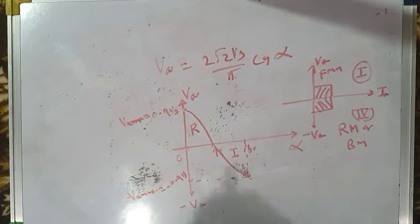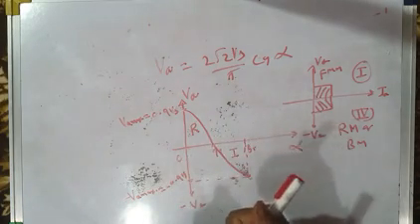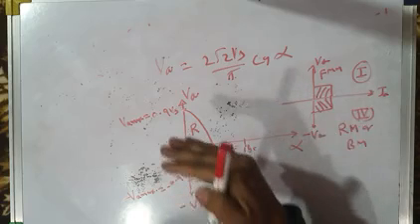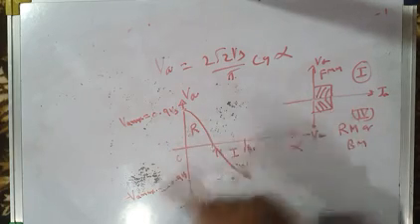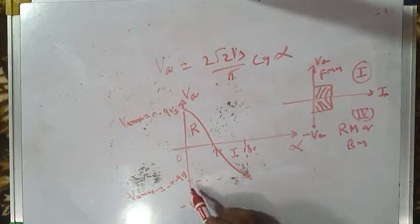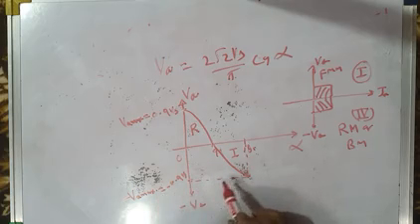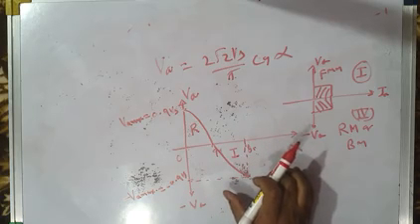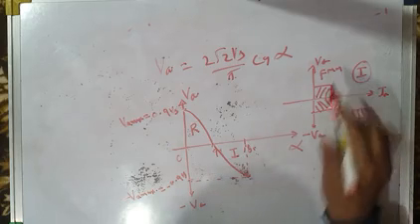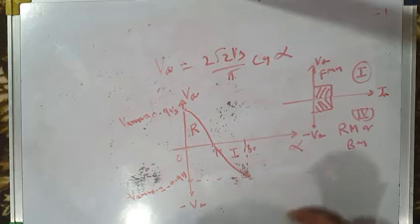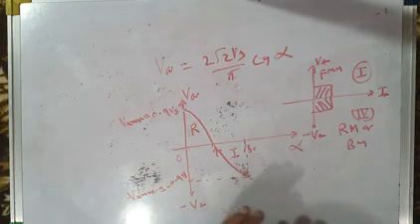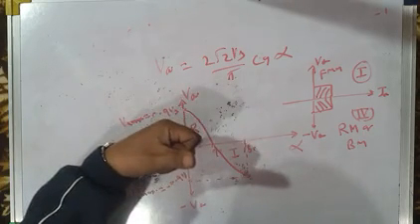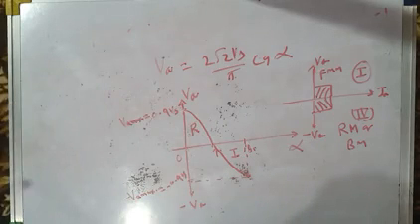In the rectification mode, your converter is taking electrical energy from the source and supplying that electric energy to the motor. Motor is operating in the forward motoring mode, converting electrical energy into mechanical energy, which is used to drive the load. From 90 to 180 degrees, our converter is operating as a line commutated inverter, not as a rectifier. It is operating in the inversion mode because average output voltage becomes negative. So our machine is not operating in motoring mode now. It's operating in the regeneration mode. It is converting mechanical energy into electrical energy, and that electrical energy is given back to the source through this inverter. So the inverter takes DC energy, converts that DC into AC and supplies that AC back to the source.